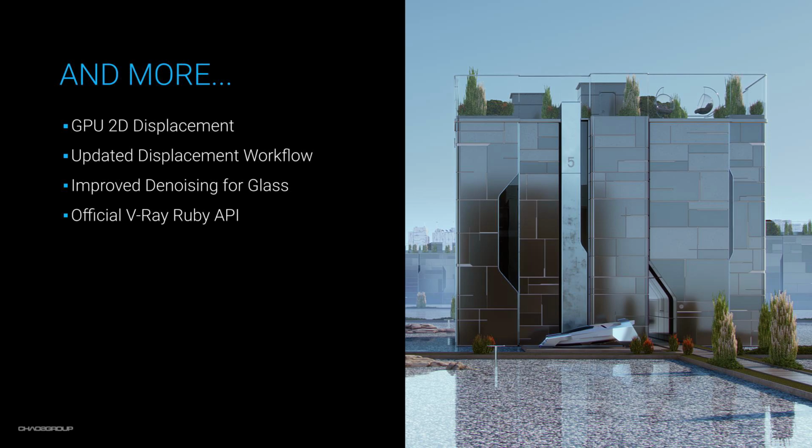We have also implemented a new displacement object modifier to simplify your workflow. Now you can apply displacement to objects in your scenes using the VRay toolbar button, as well as the new displacement parameters in the VRay Object Properties panel in Rhino. When using the VRay denoiser, you can enable the Affect All Channels option, which now reduces blurriness for objects seen through glass when using denoising.